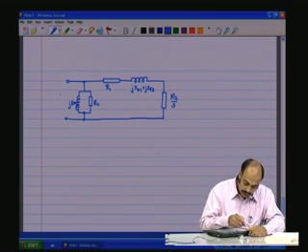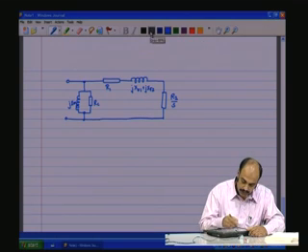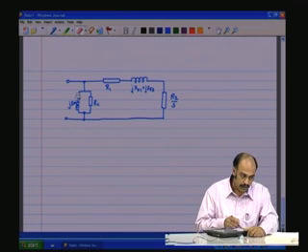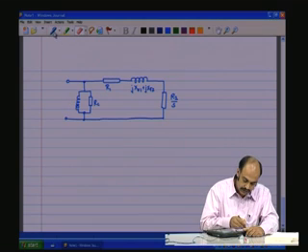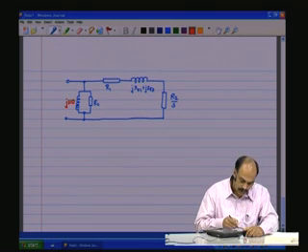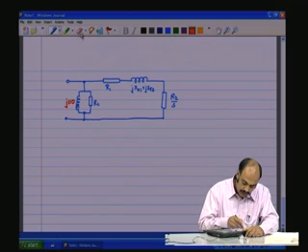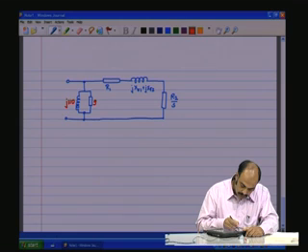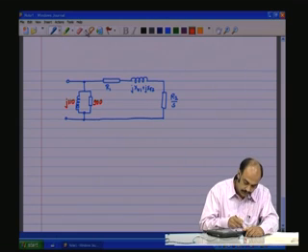Now what we shall do is that we will give some typical values of a motor to these. We shall give the magnetizing reactance a value of J110. The value for the core loss component, 900 ohms.